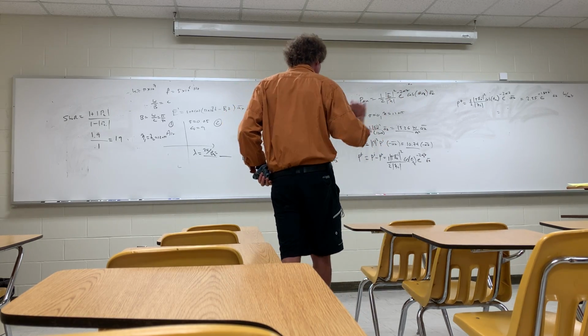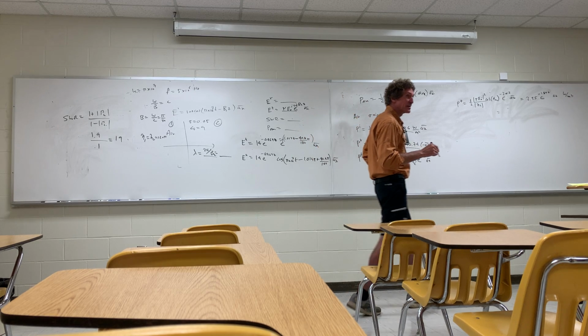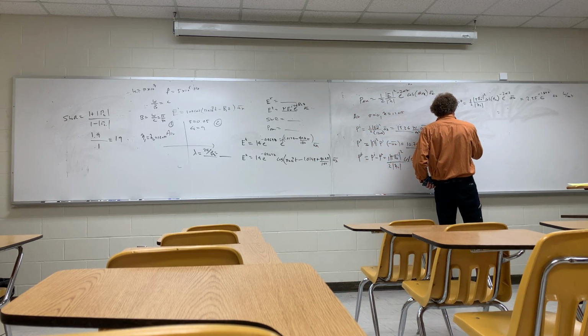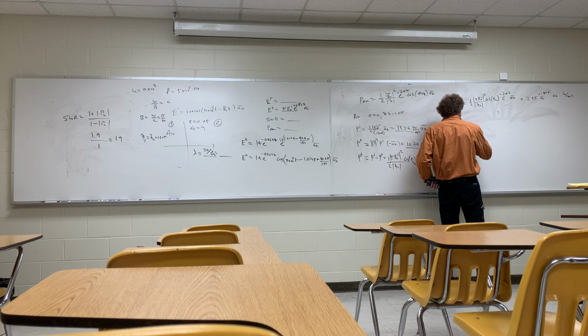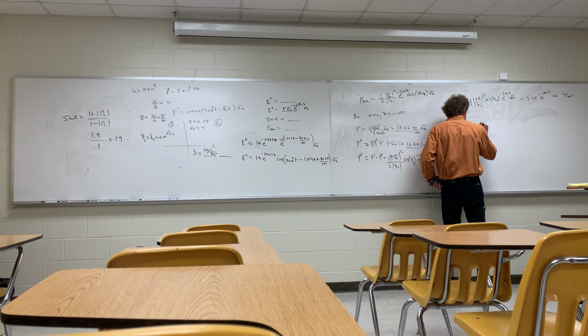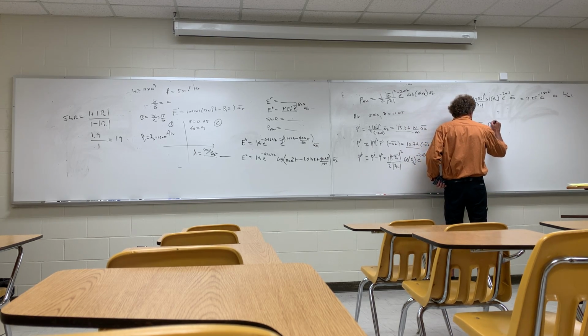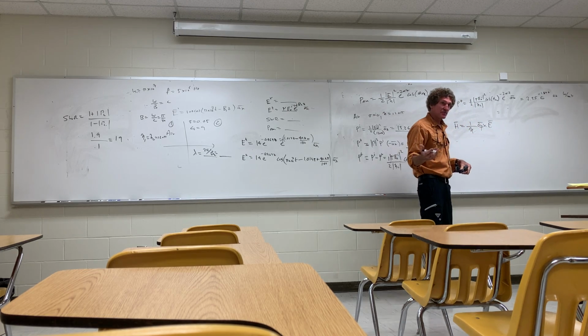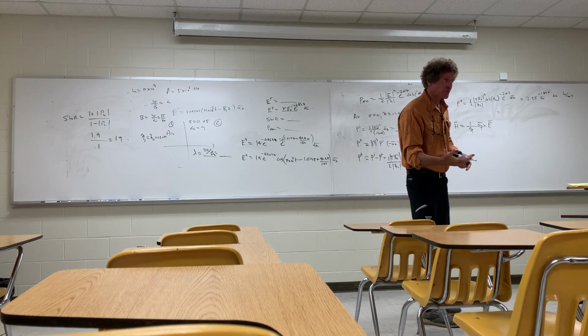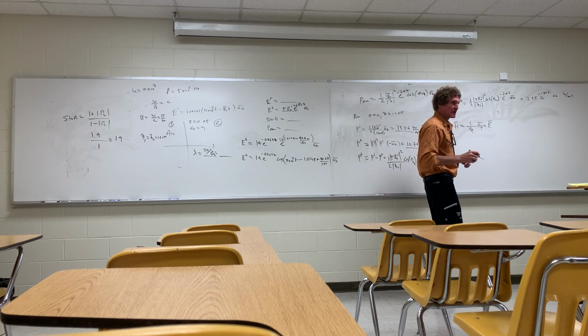Remember, this is a plane wave propagator. What's the secret? H in general is 1 over eta, right? Unit vector direction of propagation crossed into the E field. Do we have the E field in region 2? Yes, right, it's phasor form. Do we have eta in region 2?